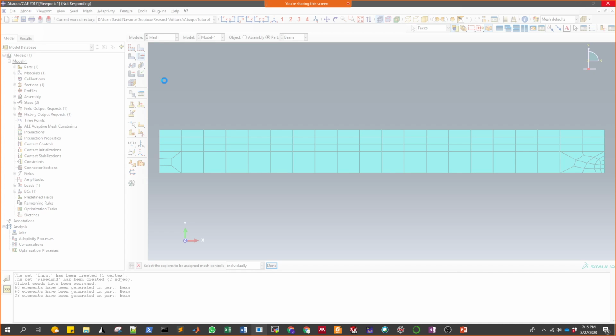Another question that might be relevant is that you might have not only linear elements, you might have higher order elements. That means that you have more nodes in an element, like having nodes in the midpoints of the edges of an element. So you can actually simulate curves in these elements. And those elements have different advantages.